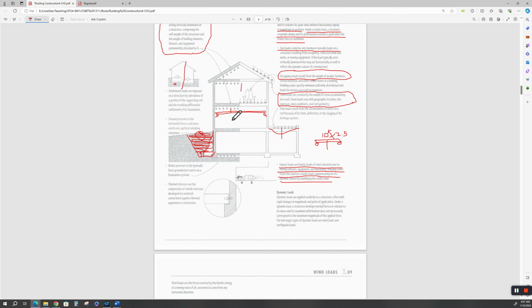And here's the top trolley for the crane, and there's the hook. This can go this way, it can go that way, and it can come in and out, right? Come forward and backwards down the length of the building. So all these factors, this way and that way, it's got to be 2.5 times 10,000 pounds. And then, of course, all that comes back down to the foundation.